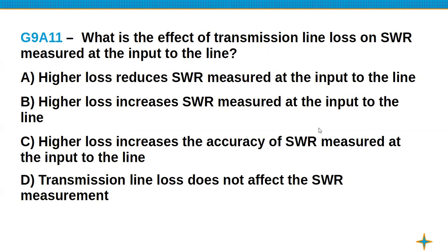What's the effect of transmission line loss on SWR measured at the input to the line? Higher loss reduces SWR. So I thought Alpha for me.